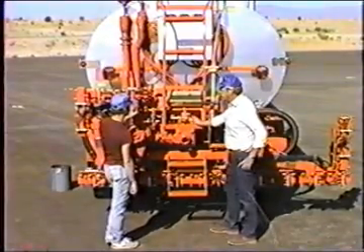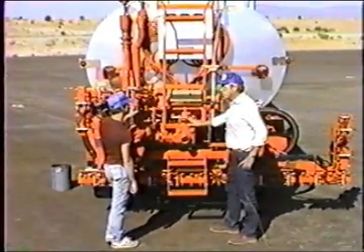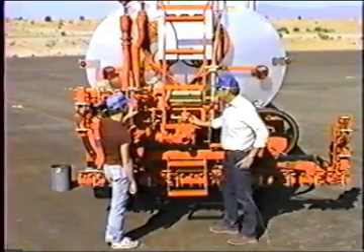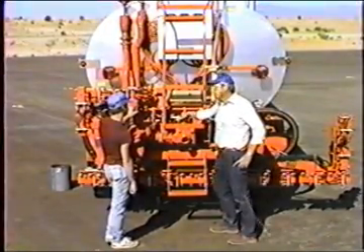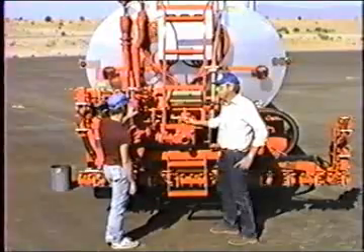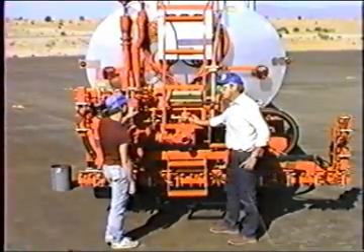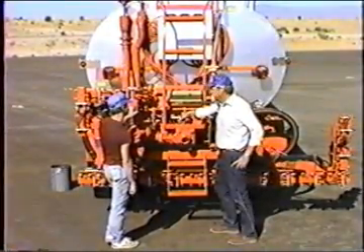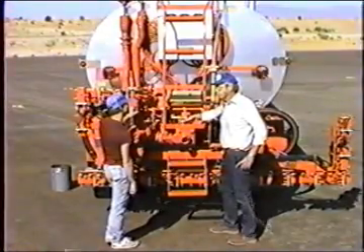If you ever have spread rate problems or loading problems, if it's not pumping right, the very first thing to check is the screens. The intake screen is the most critical. If you put a rag in that intake screen, it'll totally stop the intake into the pump. If you're asking it to put down a half a gallon per square yard, and you're only putting down a tenth of a gallon per square yard, maybe it just can't get the material. Maybe there's a rag in there, maybe there's a hat in there. Hats really plug these suckers.